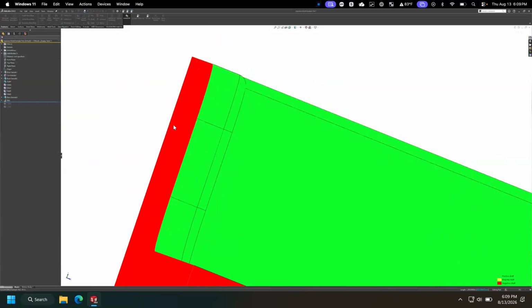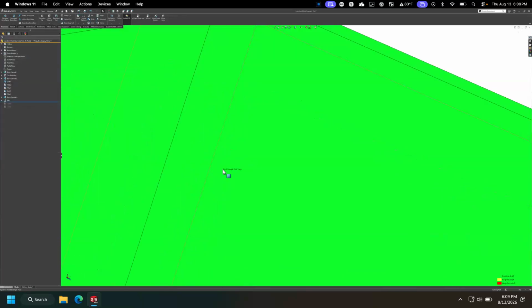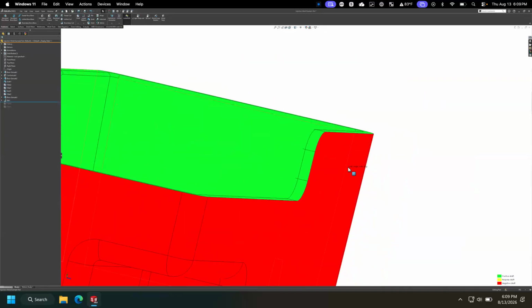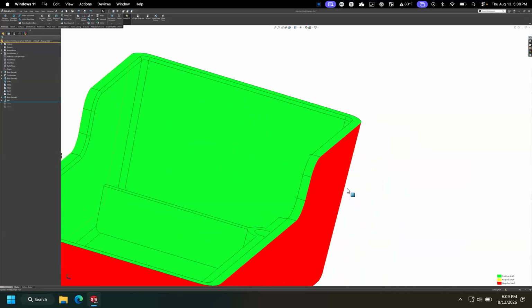The tool maker would have to split that in the center of that wall, and have half on the side, half on the other side, and you put the fillets on both sides. It will never really look perfect, and it might look pretty good, but ideally you want something like this. It's a much easier parting line.